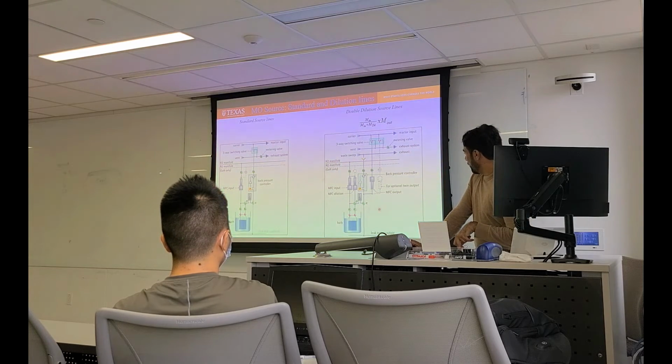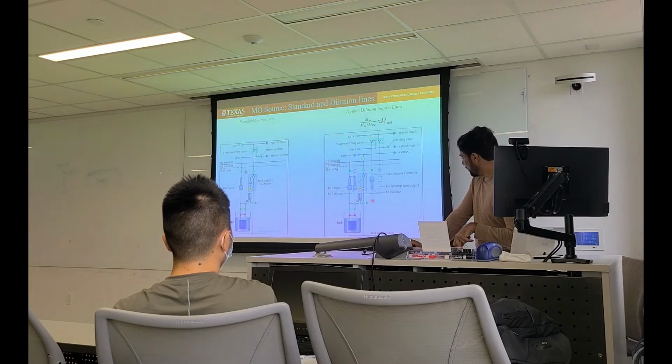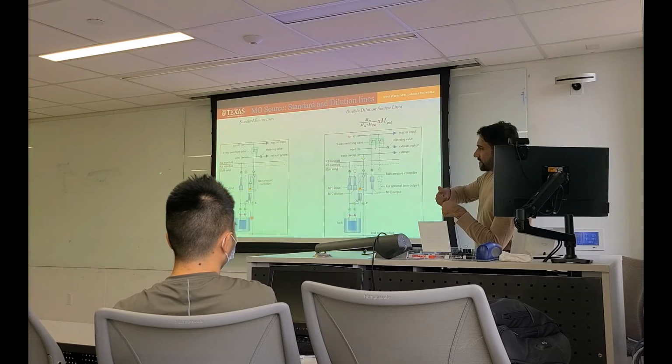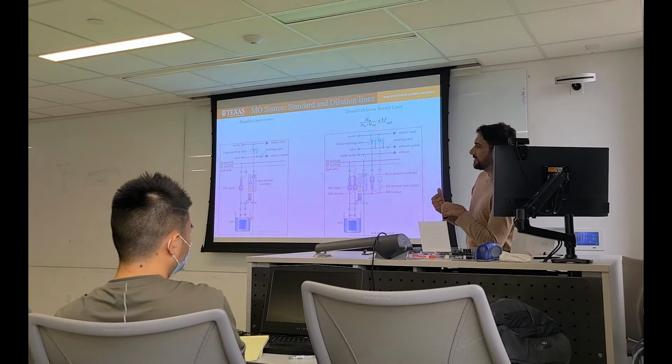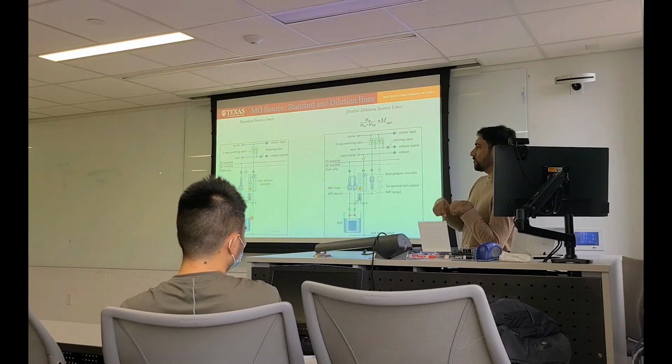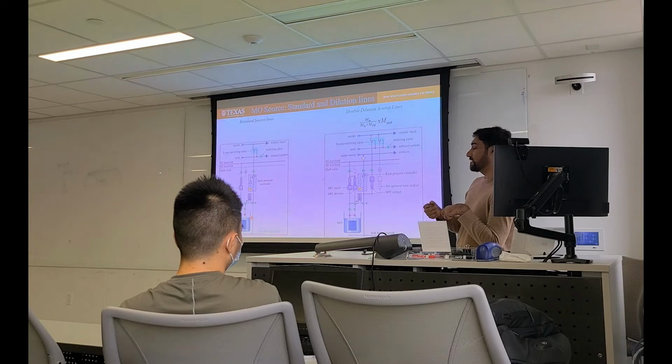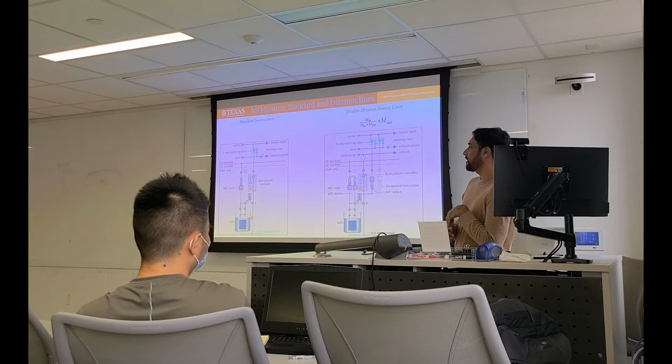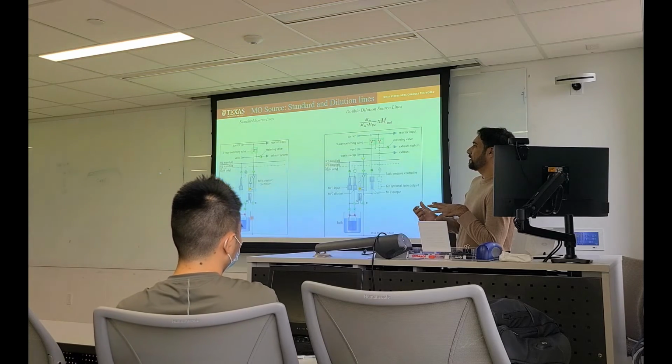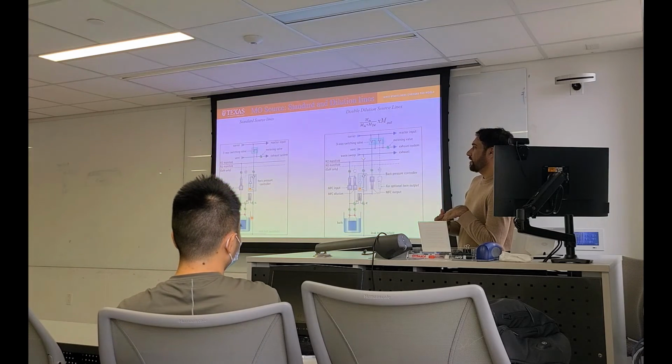So I think I have explained. Yeah. So leak test means when you suppose you have installed new bubbler there, you have fixed it, and then you want to perform the leak test. Leak test means you just flow the gas and want to see if there is any leak. So for that you need very high vacuum, external vacuum pump, and you just use the helium gas.